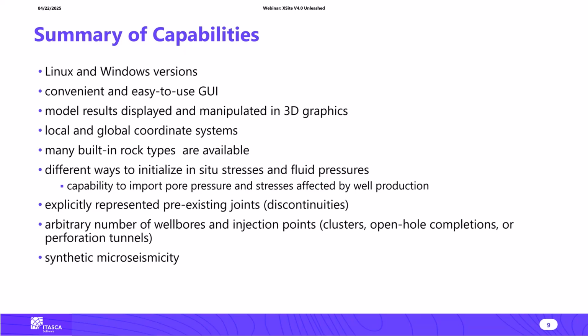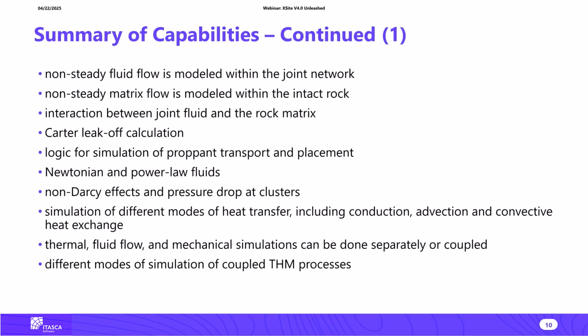The code can include and simulate an arbitrary number of wellbores and injection points, which could be either perforation clusters, open holes, or explicitly represented perforations. It can simulate synthetic microseismicity, which is a very important capability for model validation and calibration with the field data.